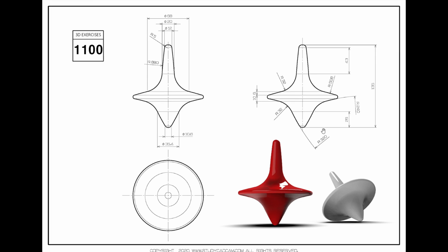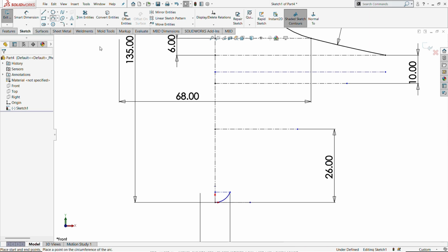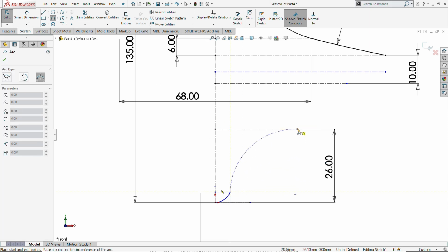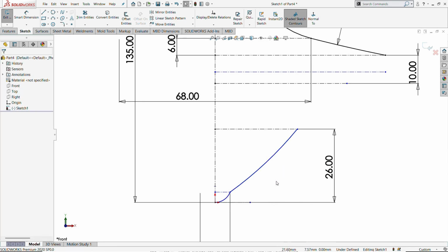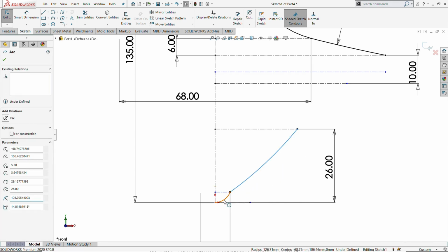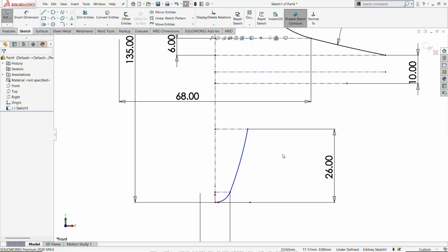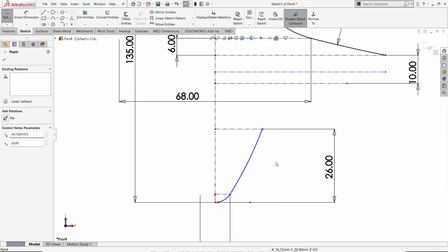What is the radius of it? It is almost 320 mm. So use a 3-point arc, start from a particular endpoint up to its endpoint, then draw a profile. Afterwards, make a tangential constraint on the bottom area, selecting both the profiles to make a tangential constraint.